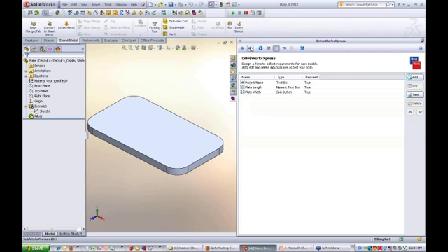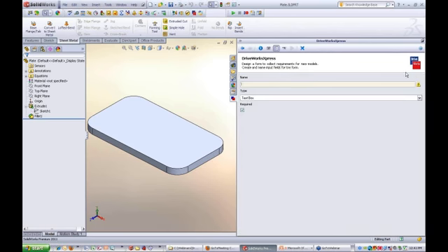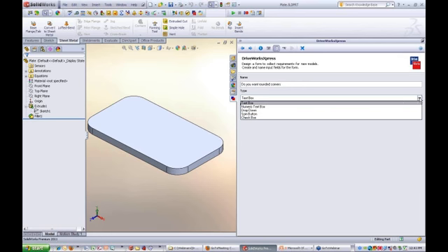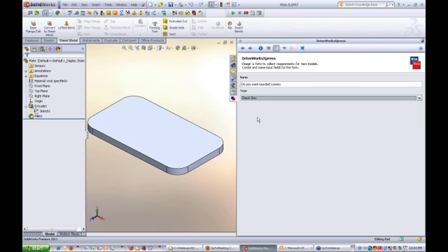We also wanted to control, do we in fact need the round corners or not. So I'll add another one. So you can see the name in the field that goes on the form can be quite descriptive, and this will be a simple checkbox, yes or no. If they tick it, yes, they want round corners. If it's not ticked, we want a square or sharp cornered plate.